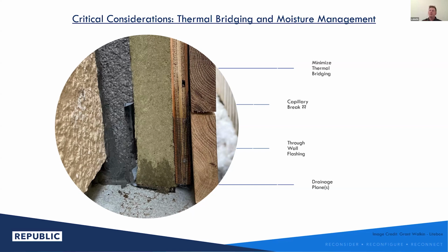And that didn't provide a ventilated cavity and made sure that any moisture that was being wicked out through that wall was unfortunately getting pulled up through capillary action into that mineral fiber. So this section of mineral fiber at the base of the wall really lost its effectiveness.